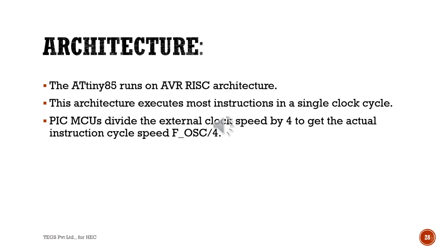Key differences to keep in mind. Architecture. ATtiny runs on AVR RISC architecture. This architecture executes most instructions in a single clock cycle. PIC MCUs divide the external clock speed by 4 to get the actual instruction cycle speed.